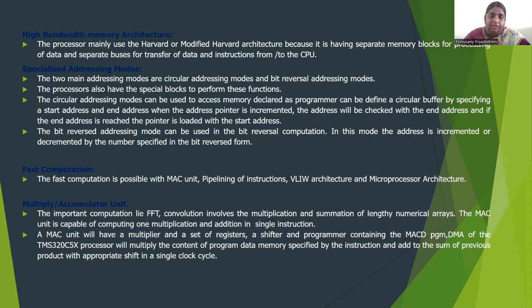Multiplier and accumulator. The important computations, such as FFT and convolution, involve the multiplication and summation of lengthy numerical arrays. The MAC unit will have a multiplier, a set of registers, and a shifter. The processor will multiply the content of the program and data memory specified by the instruction and add it to the sum of the previous product with the appropriate shift in a single clock cycle.